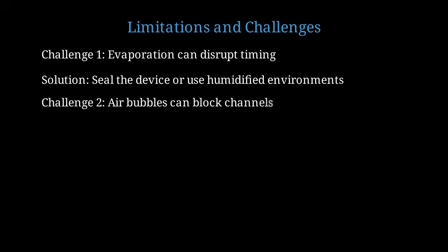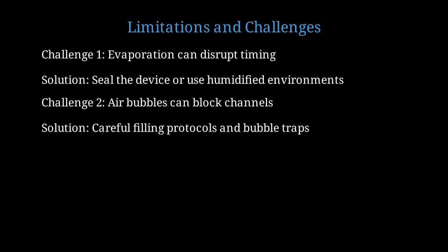Second, air bubbles are catastrophic. A single bubble can block a channel completely because surface tension prevents liquid from flowing around it. Solutions include careful filling protocols to avoid introducing bubbles and designing bubble traps that capture them.